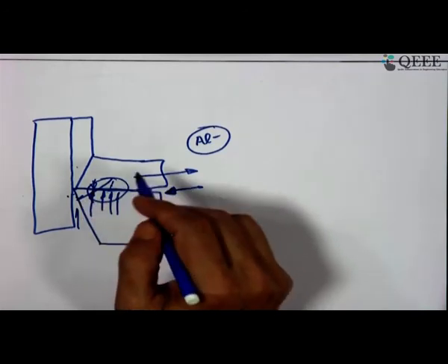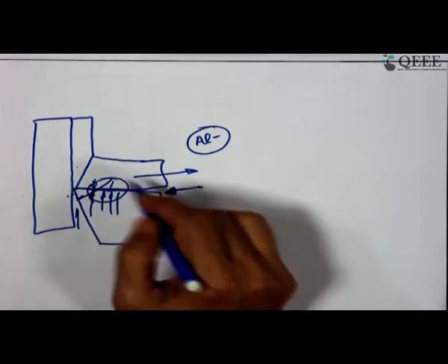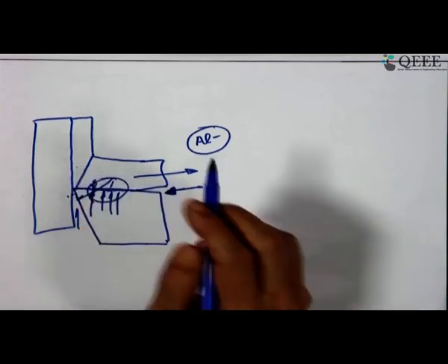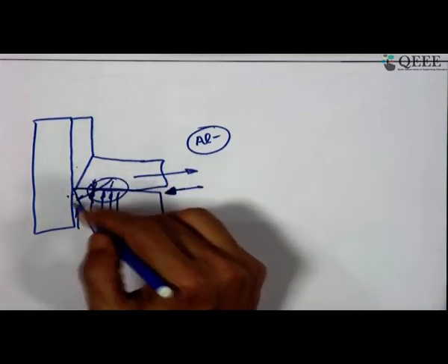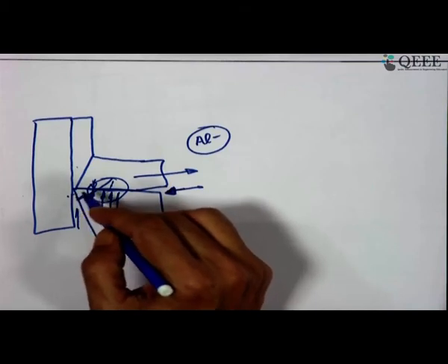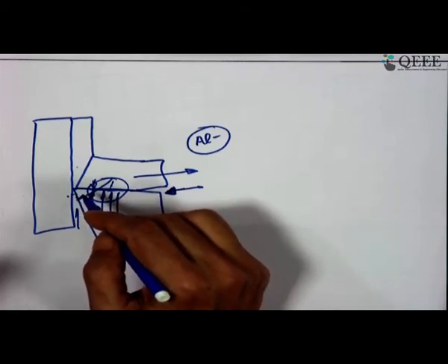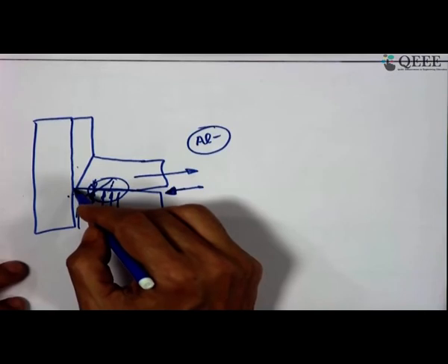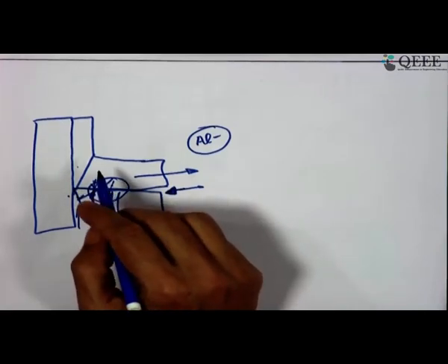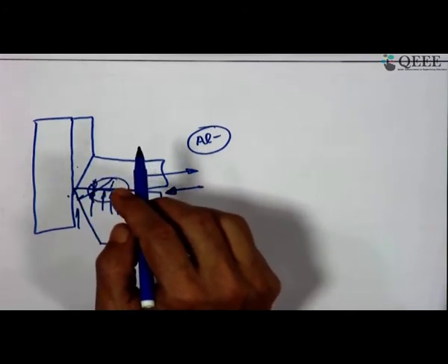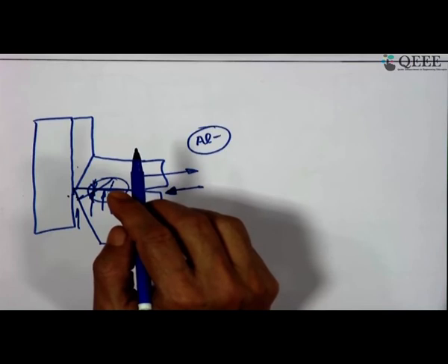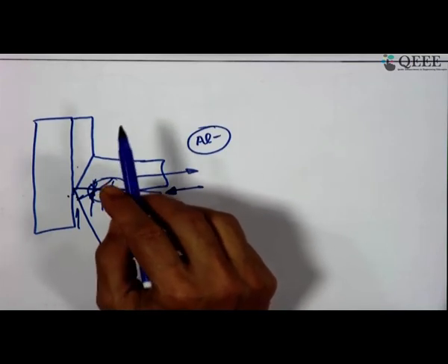Bulk cooling may help your workpiece, but as such may not help in retarding the wear, because it is the concentrated place where the wear is taking place that needs to be targeted, to have immediate and rapid cooling and immediate benefit.